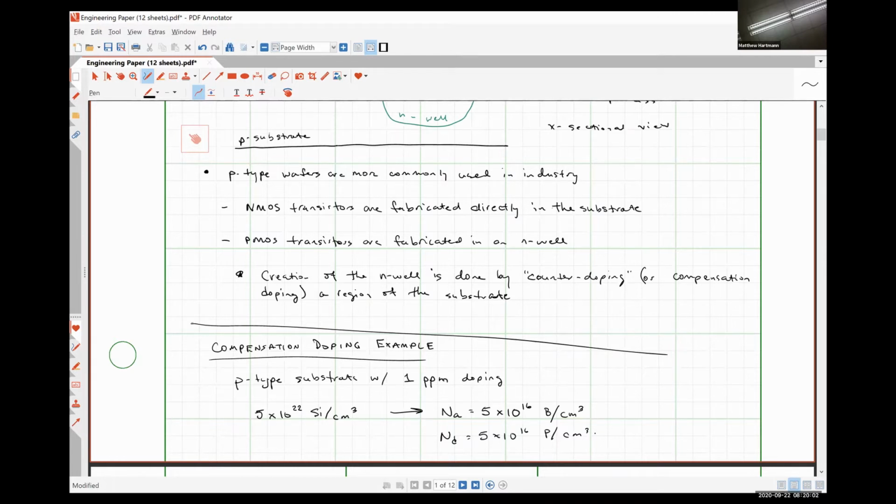There is a little bit of a downside to this, but we'll talk about that in a moment. Now, I've made the region electrically neutral, so I don't have an N well, I just have a place that doesn't have any free charge carriers effectively. So I'll need to go beyond that level. Let's say 10 to the 19 donor atoms.